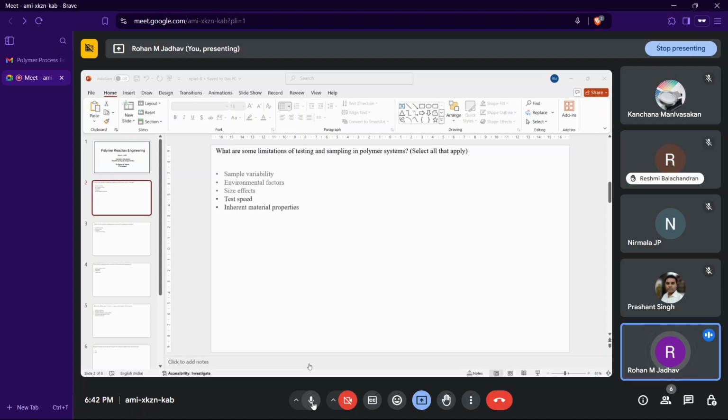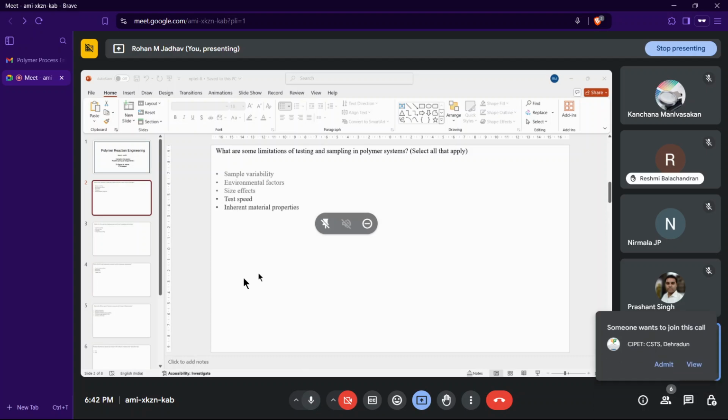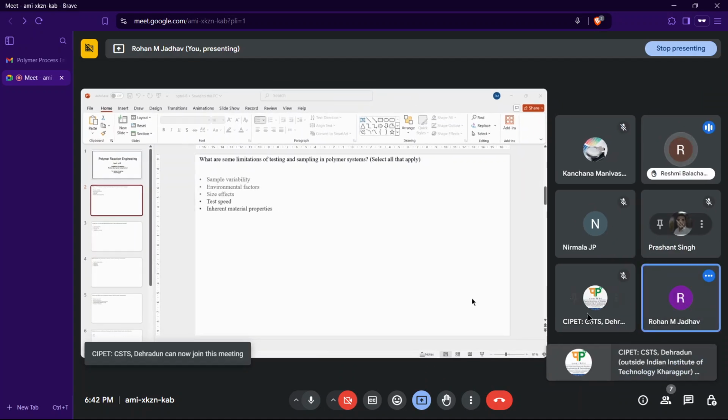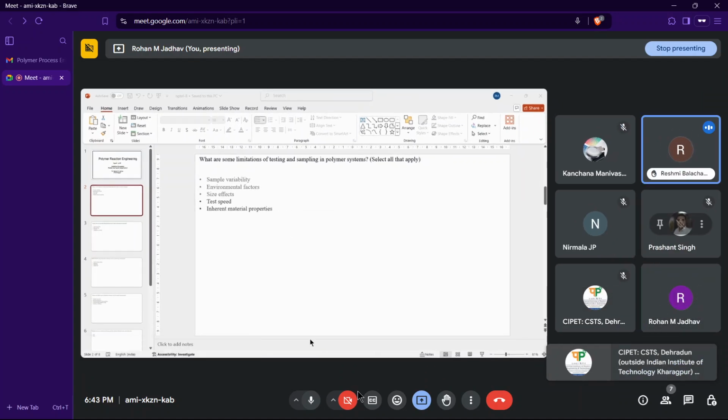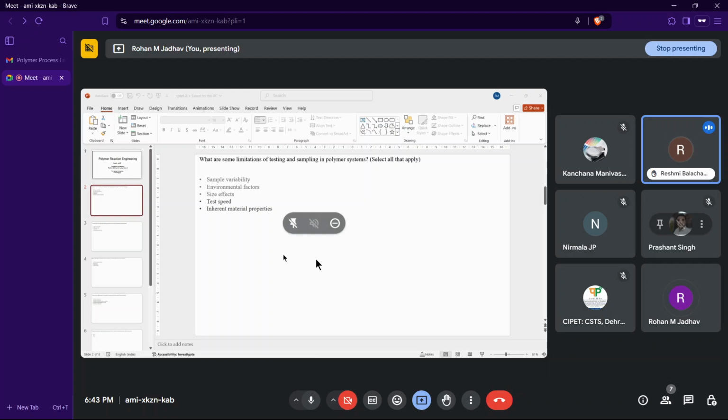See, the difference between pourability and melt flow is that in melt flow, you are melting the polymer and seeing how it flows when you apply some pressure to it. But in pourability, you are basically using a flow cup to measure the pouring ability of the polymer itself. Okay, understood.